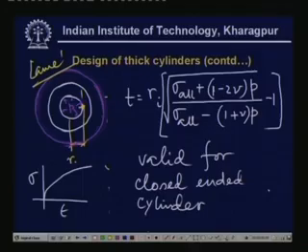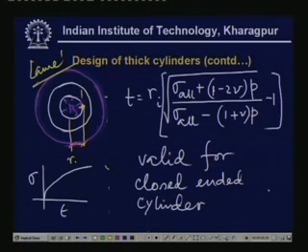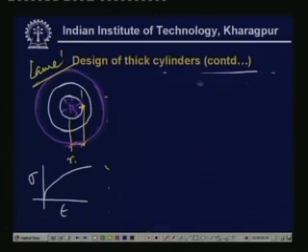These are the three expressions which are normally used while designing it, but if we want to design the pipe for a very high pressure, then sometimes we use the hoop stress formula, that is the same expression as for the thin cylinder, but instead of taking the average diameter, we take the outside diameter. Now we see what will be the thickness for a high pressure.